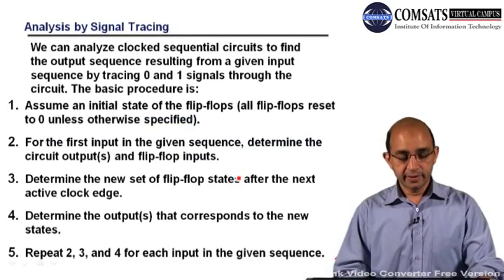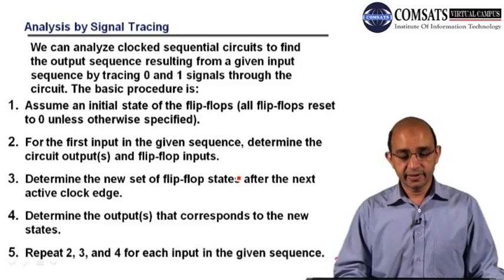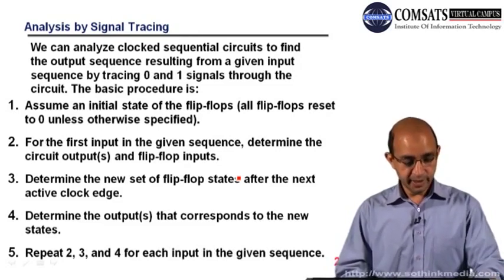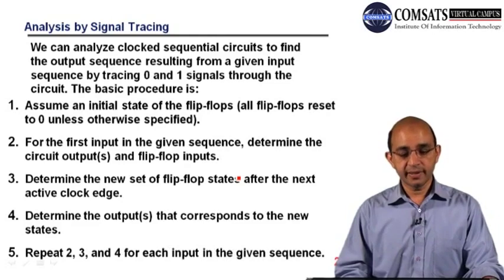And we will be discussing circuit analysis, sequential circuit analysis, and in addition to design. Today regarding the analysis, we will be discussing sequential circuit analysis by signal tracing. And when we talk about sequential circuit analysis by signal tracing, we will be assuming that we are analyzing clocked sequential circuits. So we have to go through a certain number of steps.